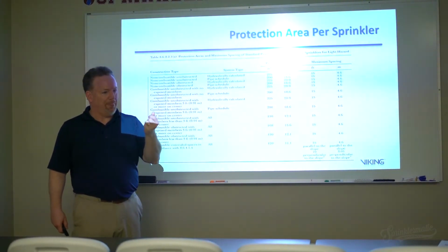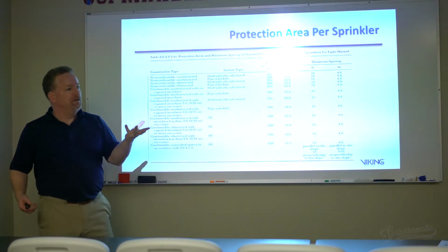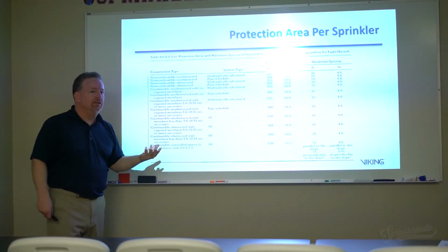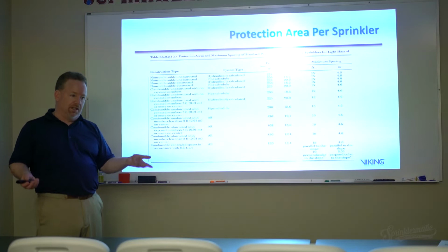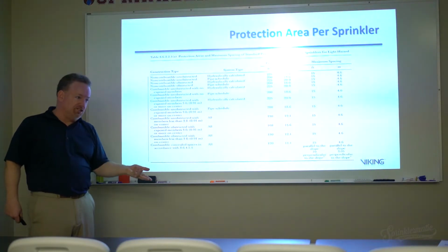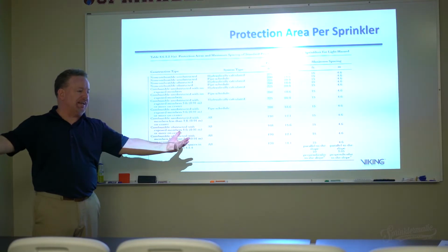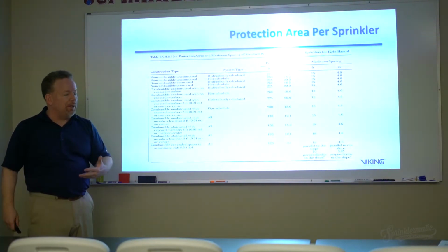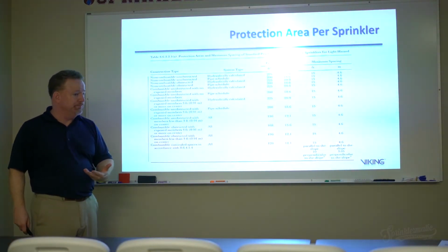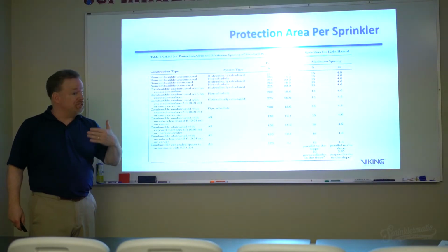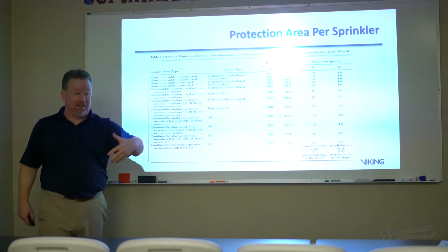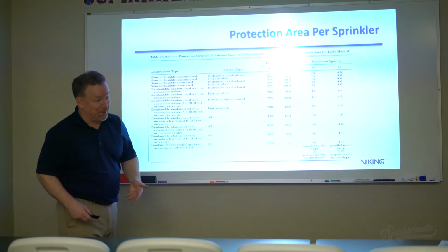Less money and get more coverage. Fewer sprinklers installed usually means a less expensive system. The challenge is that in order to get that extended coverage, you're going to probably need to have greater pressure. Okay, so it's not just a free-for-all. I mean, otherwise everybody would be doing it.